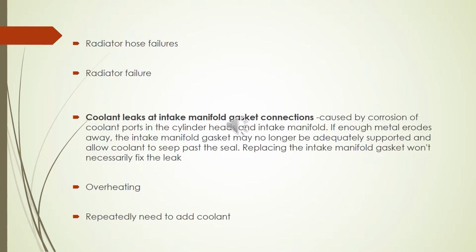Overheating, and overheating is a very big problem because it can cause the head gasket to blow out, and this will lead to some of the coolant getting into the combustion chamber, and this will cause the destruction of the engine. You have to repeatedly add the coolant each and every time.